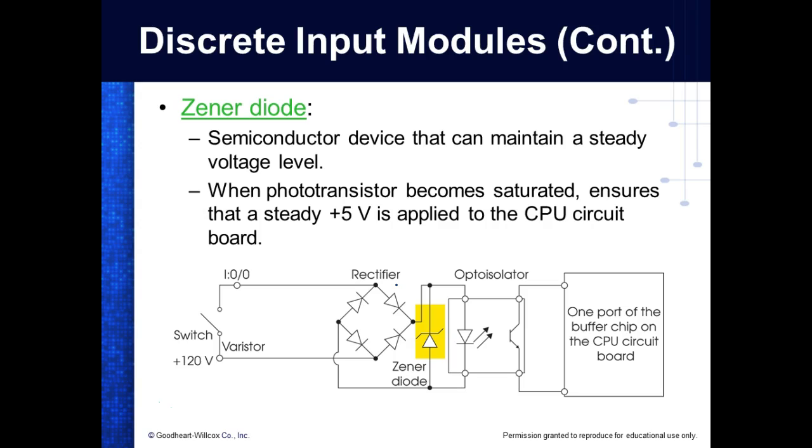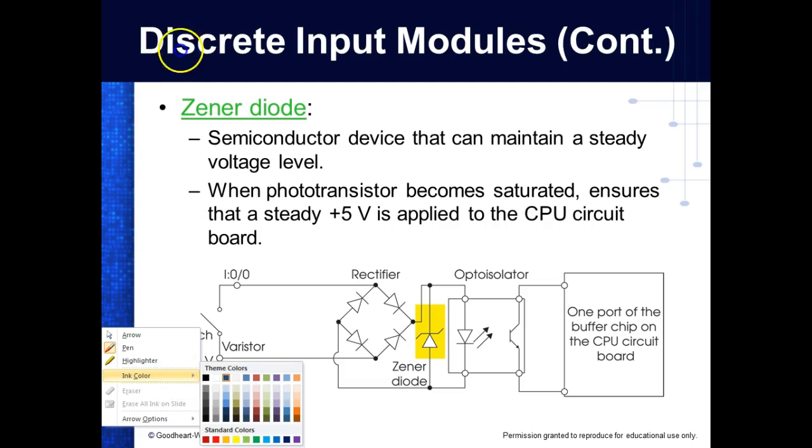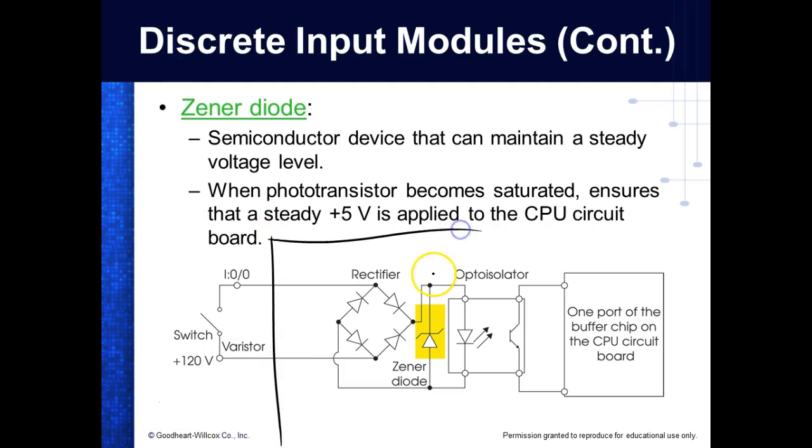All you're looking at right now is you're looking at it where? This is where you're at right here. This is what we're dealing with. All we got to do is establish a common, and then what we call a hot lead, which we'll look at. And the same thing's true on outputs. Except output, we add another. So on the inputs, they're either going to be DC or AC. Period. On the outputs, we got 3 options. We got AC, DC, or relay. And what's nice about relay is that you can wire it AC or you can wire it DC. Either way.